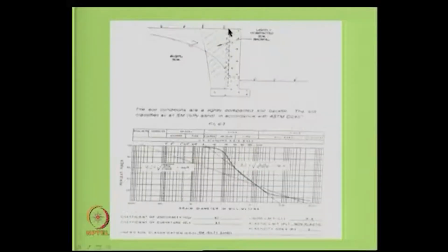Okay. So, this is another example of why you provide drainage behind the retaining walls. Otherwise, the seepage pressures also should be considered in design, right. It is not gamma h square by 2 that you use. Again, you have to take into account gamma w h square by 2, like saturated weight, water pressure, whatever is the water pressure due to that also should be considered, which is going to be very expensive. So, the best way is to drain the water and have proper provisions.